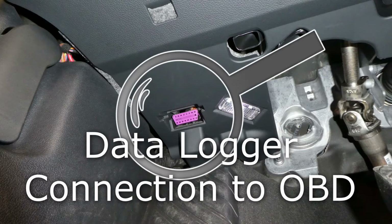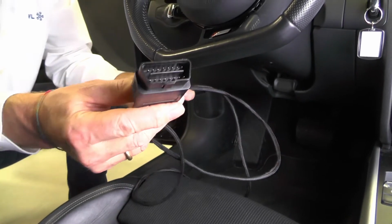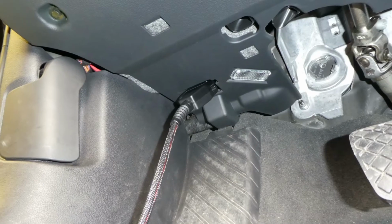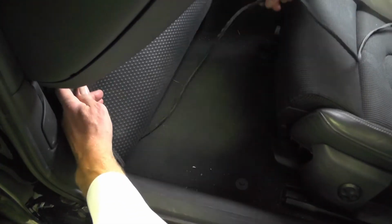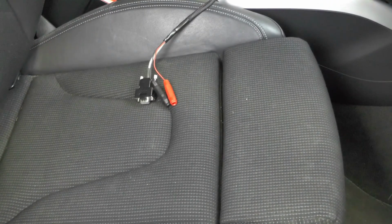Connecting the onboard diagnostic interface of a passenger car with a CAN data logger is the easiest way to access vehicle operation data to combine with the fuel consumption measurement. The standardized OBD connector, pin layout and output parameters are universal for all car makers. However, message protocols are individual.